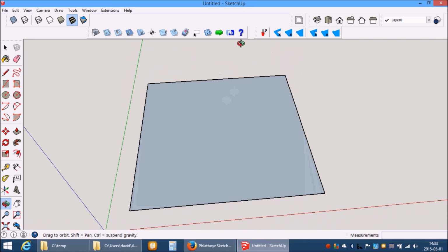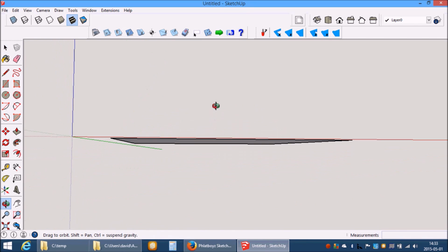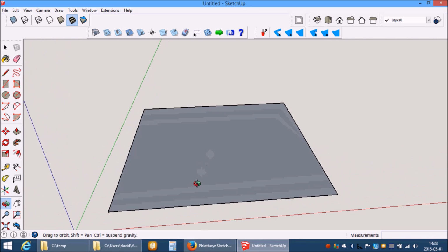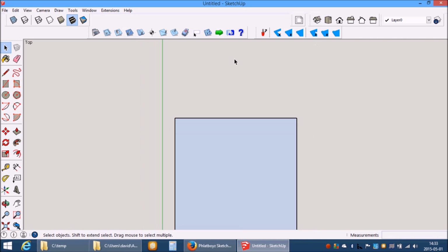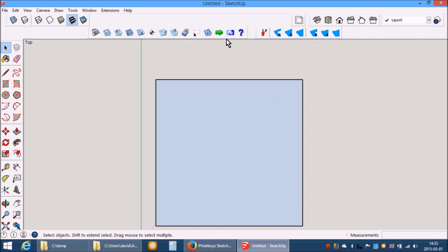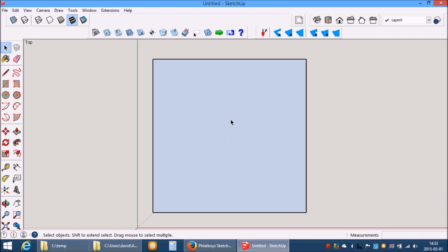You will notice that this drawing is flat and level with the XY plane. If you do your drawing any other way, it will not work with SketchUcam. SketchUcam is designed around flat drawings rather than three-dimensional drawings. There are a number of plugins free on the web to help you convert three-dimensional drawings into projected flat part segments, and you can use those or do it manually as you choose. I'm just going to do some simple things on this drawing to illustrate the various tools available.